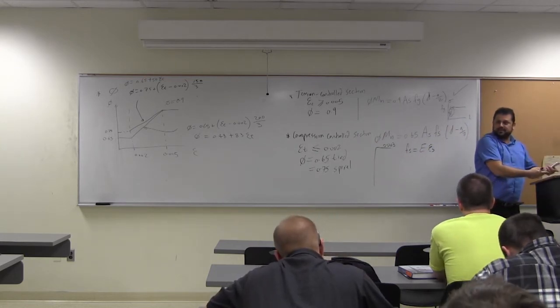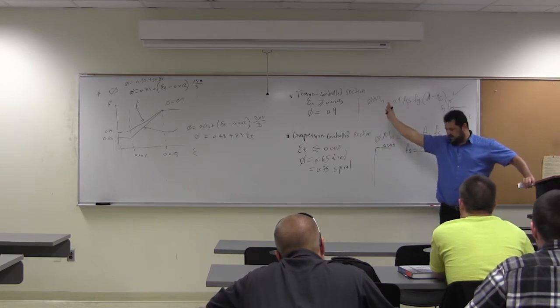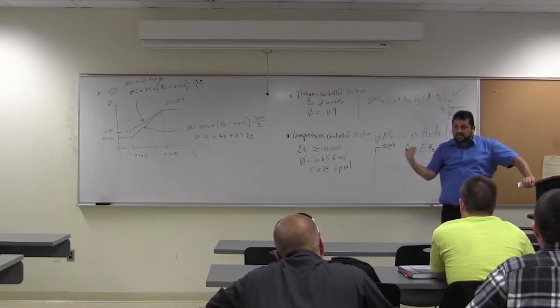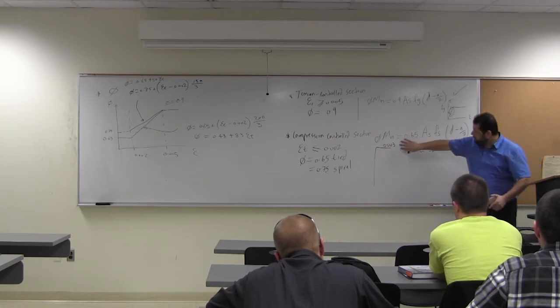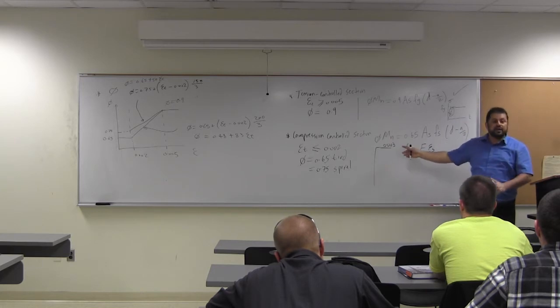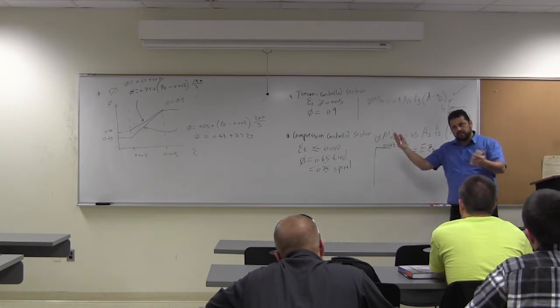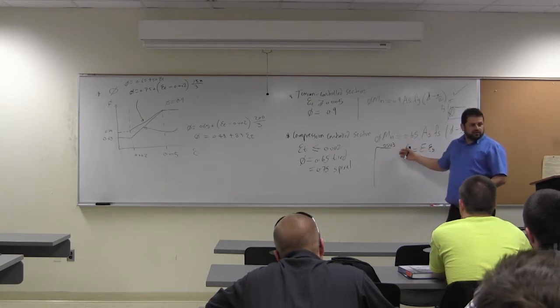Now you look at the steel. What's the strain in the steel? Did it reach 0.005? Tension control. Did it yield? Something else. Is it less than 0.005? Compression control section. So this point is a reference point, given. Without it you cannot solve it. Without this one we cannot solve. We have one more unknown. We need to find something else. So this is defined or considered by the code.